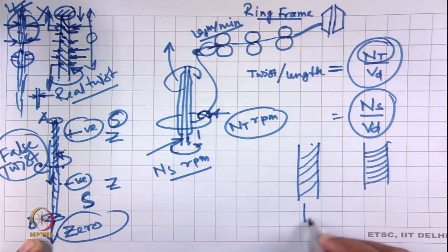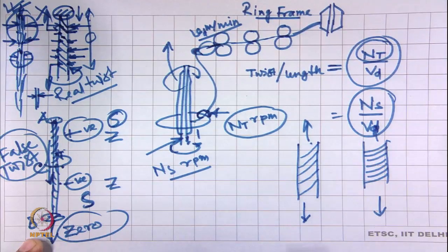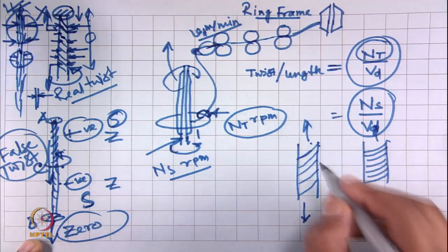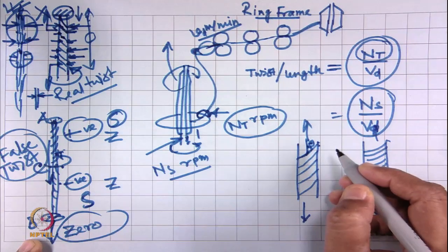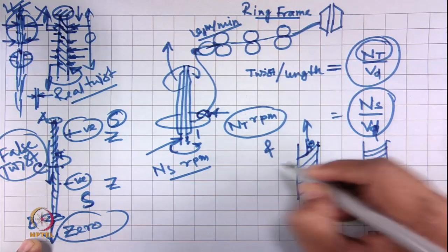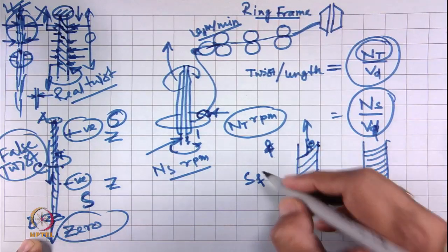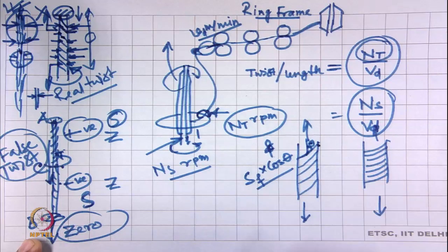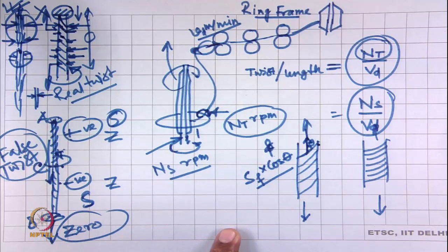When the load is applied on the yarn, if the angle is theta, the component of fiber strength will be as follows. If S is the strength of the fiber, its contribution towards yarn strength will be S cos theta, and that cos theta component will be along the yarn axis.